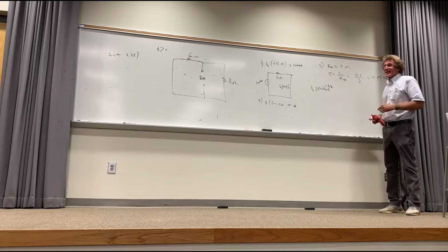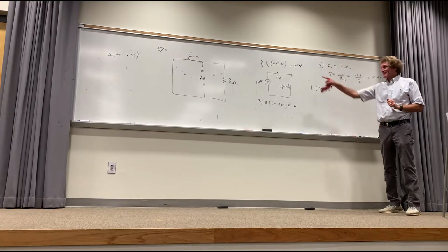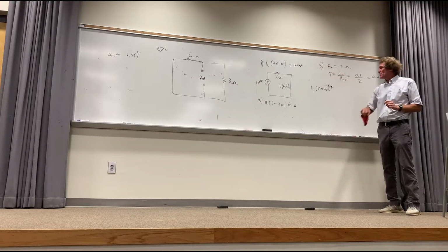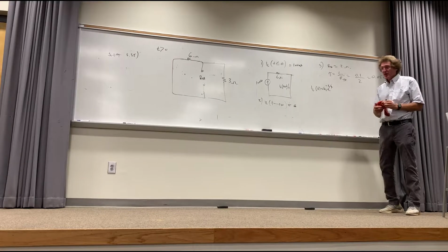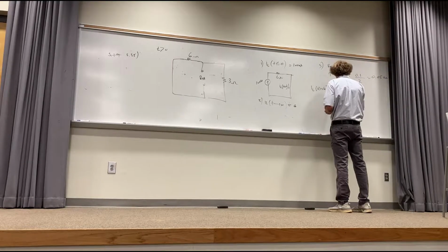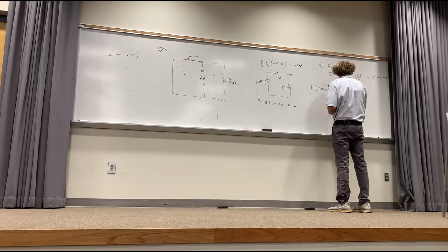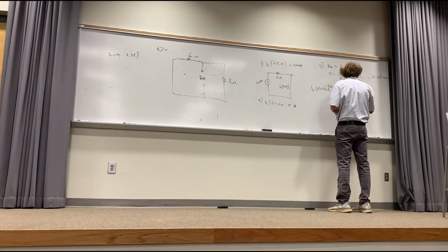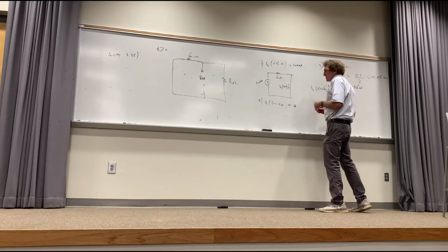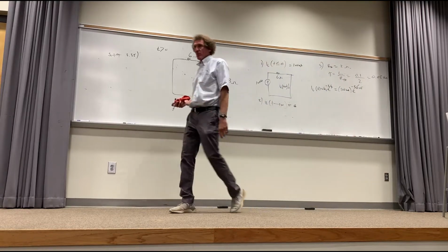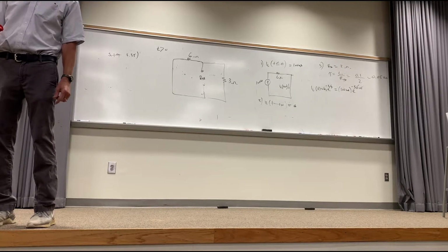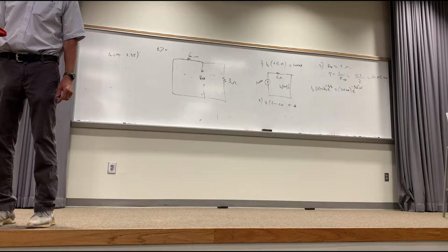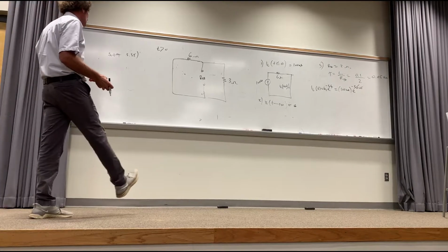Now, what's K1? At t equals 0, it's 100 milliamps. At t equals 0, this goes to 1. K1 is 100 milliamps. Do y'all see that, class? So that means IL going through that inductor for t greater than 0 is going to be 100 milliamps times e to the minus t over tau, which is 0.05 seconds. Or you could say e to the minus 20t if you want. Agreed? What did they want in that problem? That's IL. Did they want something else? They wanted the current going through the resistor 6 ohms.